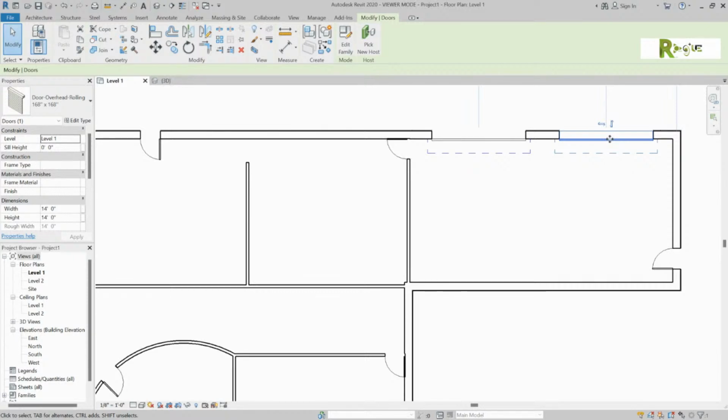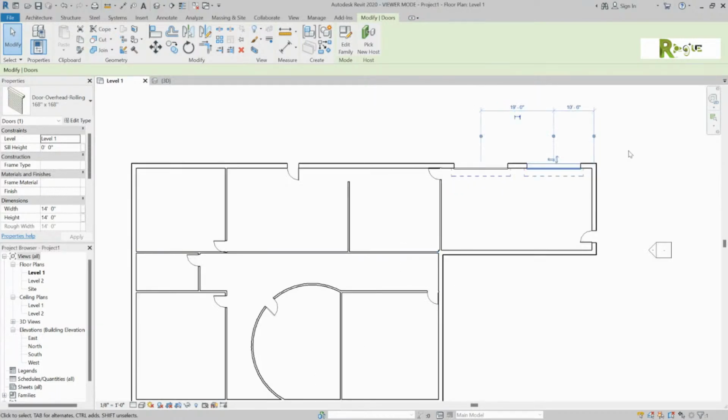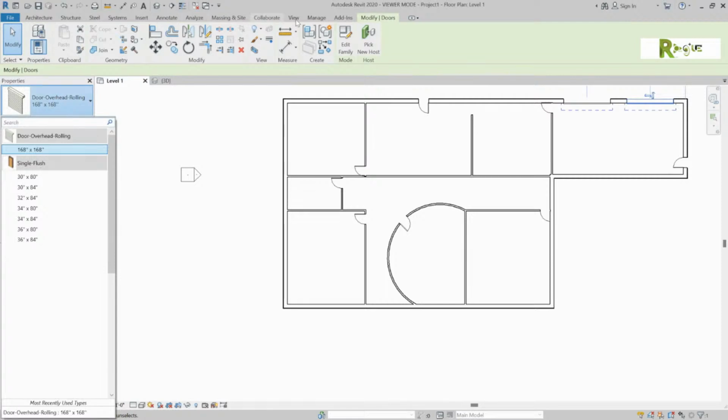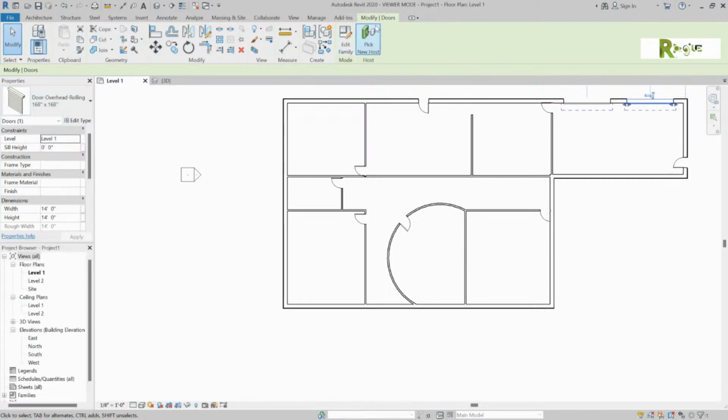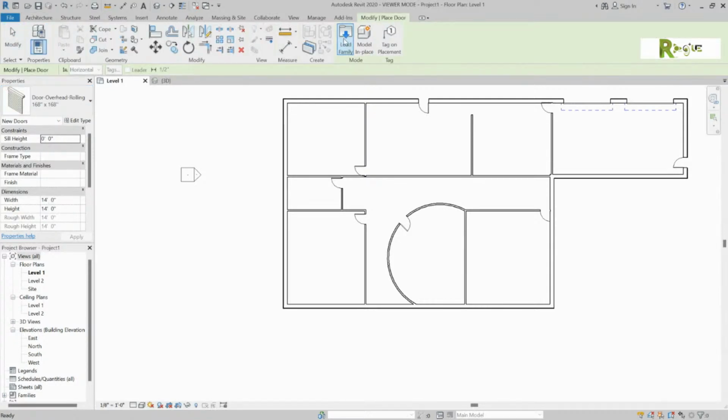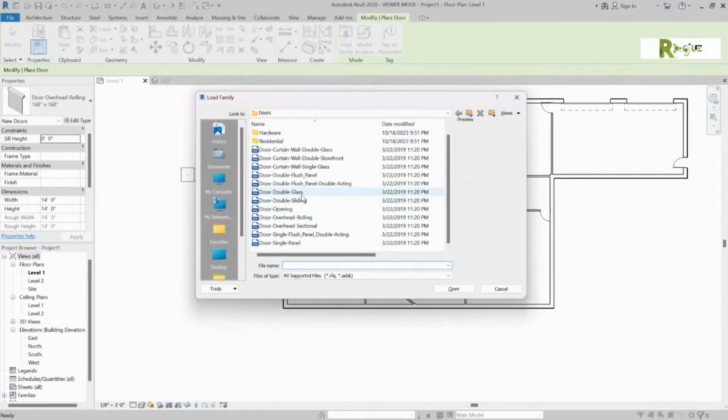Okay. Why don't you put a nice double door wherever your front door is? So remember how to do that? What you would be doing right now is changing that door that you've got selected. Got to hit escape 2 times. Get off of that object. Go back to door. See how the window, that thing came back up? Load family. Perfect. Double glass. I love it.